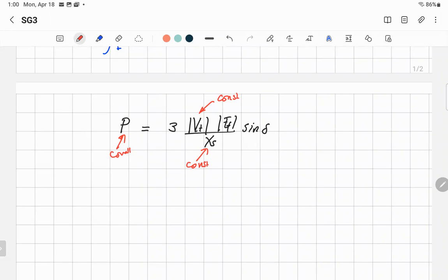Well, they said that the field current changed. What is the effect of field current? The magnetization curve is the relationship between IF, the field current, and the induced voltage. So if you increase IF, you will increase EF.